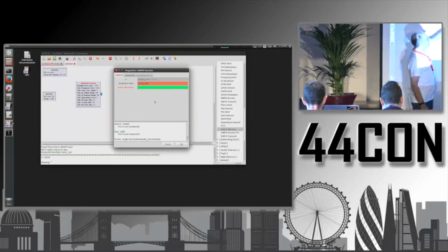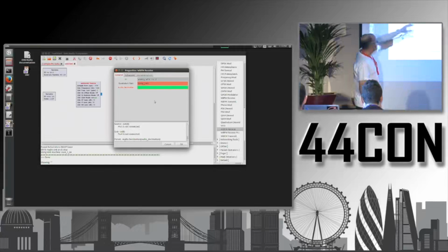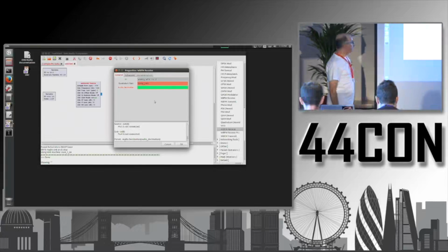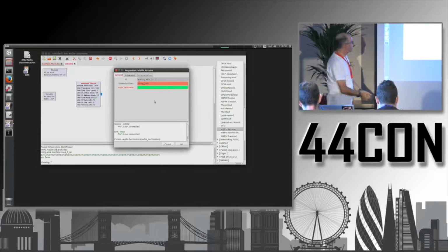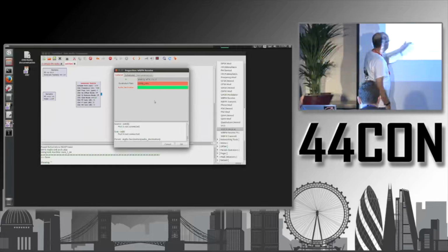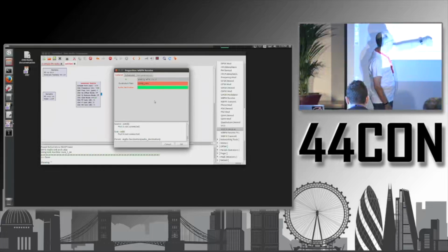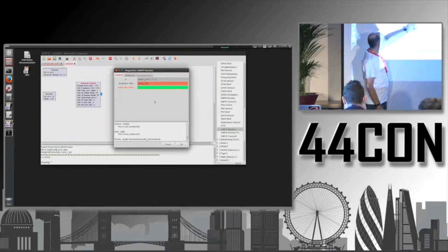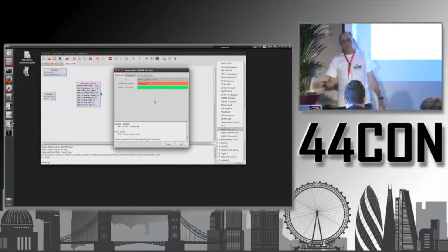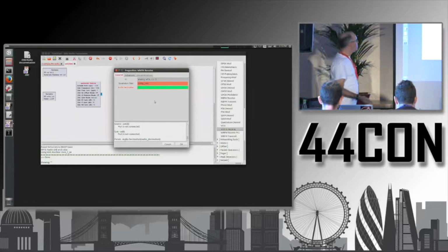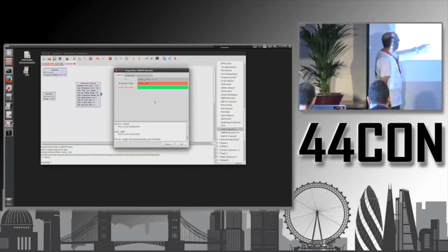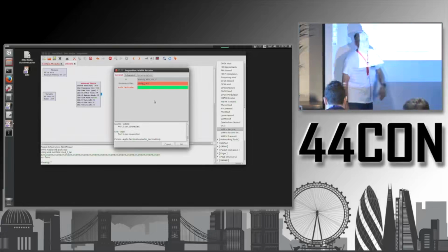So this WBFM receiver works with a quadrature rate and an audio decimation to do the demodulation. Those are two parameters that you have to provide. And for the quadrature rate, you can provide the sample rate. And then the audio decimation, that will be a number, an integer, that will be used to divide that sample rate.